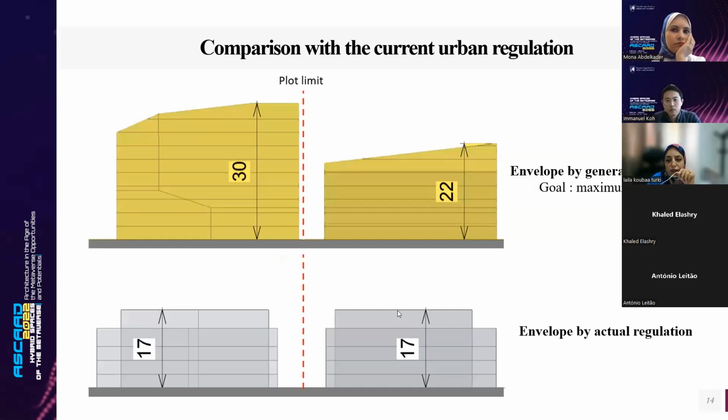The comparison of the results obtained with the current urban regulation of Tunis shows a clear improvement by using this model. We notice that this approach improves the maximum height indicated by the urban regulation. It can increase until 130 meters compared to 70 meters as indicated by the actual urban regulation. And the model allows a higher building guaranteeing solar access.